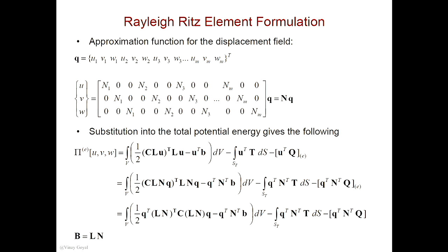Second row there, you can see I've shifted everything 1 to the right, and these are zeros. That's done on purpose, so that when I multiply this second row times this column, I get 0 times that, n1 times v1. See that? Times 0 times w1. So now again, anything that has v's is active now. Everything else is not active. So that way, my displacement v, my vertical displacement, or along the y-axis, is interpolated with the nodal values that are basically v1, v2, v3, and so forth.